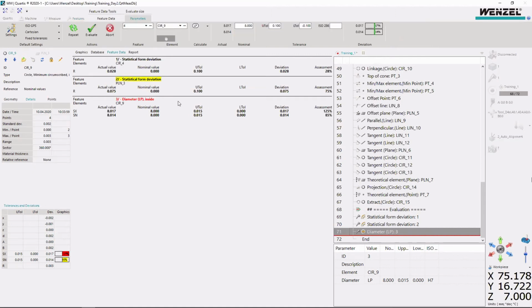Okay. Then the next one, square, will be similar. It's just a calculation issue. And then here is the envelope requirement. Basically the envelope requirement is based on whether you have an inner circle or outer circle. If it is an inner circle, then it will consist of either maximum inscribed and the 2-point size, so you will have 2 results also.